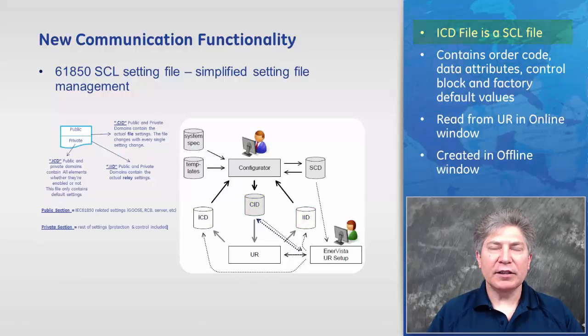The ICD is the IED capability description file, and it's a station configuration language file that describes a UR with a particular order code, data attributes, control blocks, and factory default values. It contains both public and private sections, and can be copied directly from the UR device or from the EnerVista UR Setup.